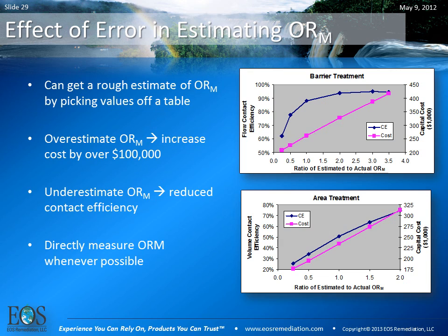You can send samples to Microbial Insights, I believe is one vendor that will do this for you, and it's a simple small column test where you run the oil through the column and you see how much sticks, so it gives you an idea for your site how sticky your oil will be to that material.